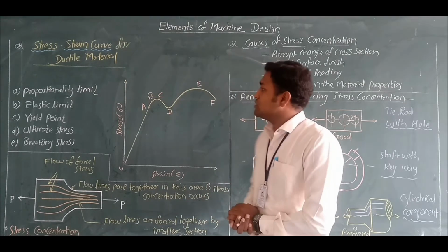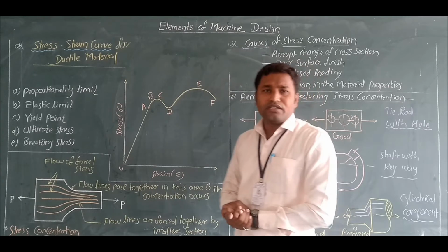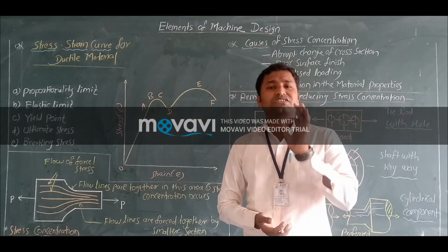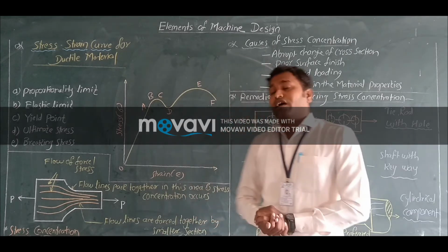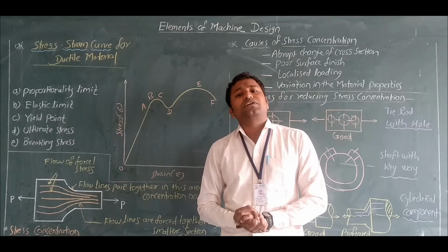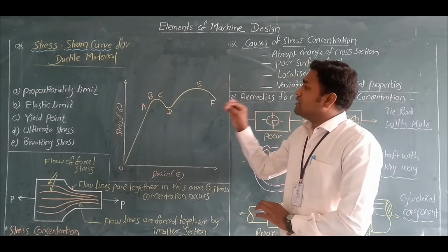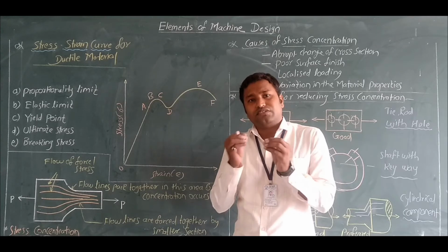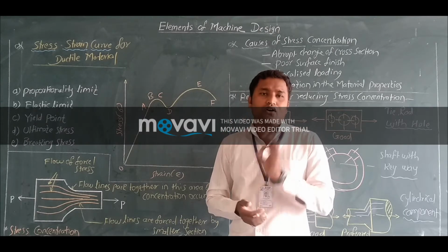At this yield point, when increasing the stress, the plastic stage will be reached. Up to this point the elastic property has not been exceeded. When the material is loaded beyond this, the change in size and shape will not be recovered.